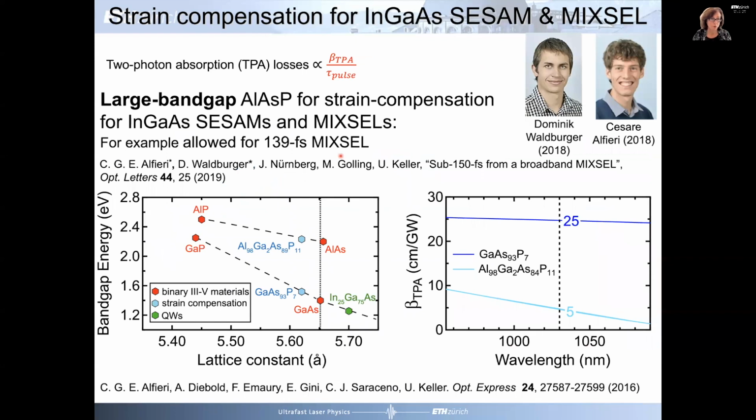In addition, for active devices and even for systems where we use more than just one indium gallium arsenide quantum well, we need to start to worry about strain compensation. So the indium gallium arsenide here at around 1 micron, when you look at the lattice constant, is introducing a strain on the gallium arsenide, aluminum arsenide DBR mirror. So you can then use different materials and introduce phosphorus into it to do the strain compensation.